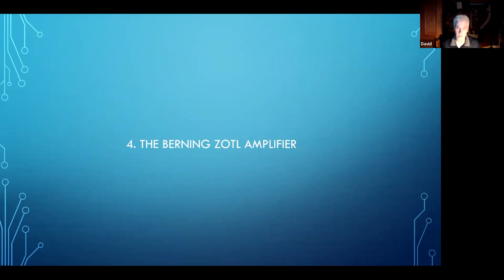My idea behind this was to circulate the full current all the time. So you stayed away from crossover notch problems, crossover distortion, things like that, because you'd be circulating the full current all the time, but returning it to the power supply continuously. So it wasn't dissipating a lot of heat.